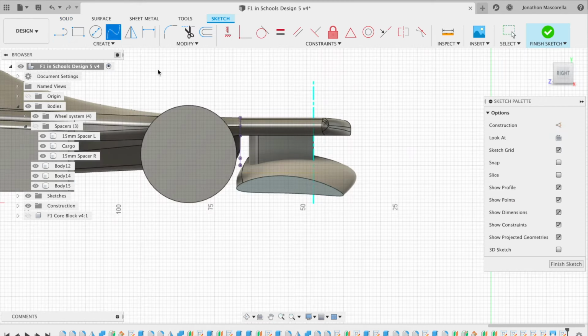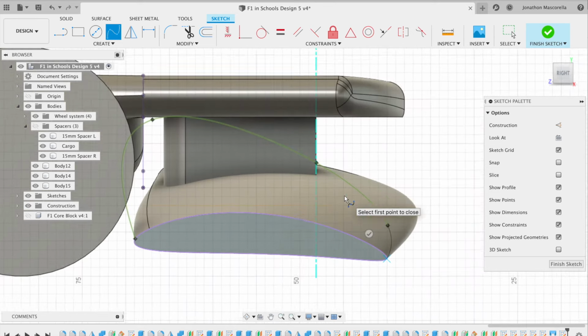And now by creating a sketch on the end of the wing here, I can do the wing tip, and then once the wing tip's complete, we'll be able to mirror it. And I do a little bit of shaping around the edges here just to make the edges a little bit more curved and aesthetically pleasing. So yeah, check it out.